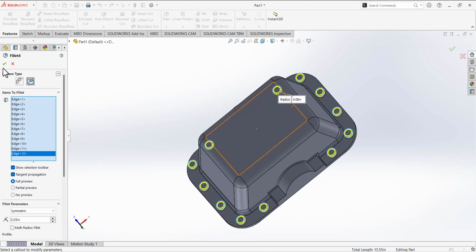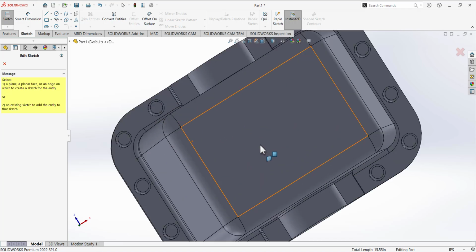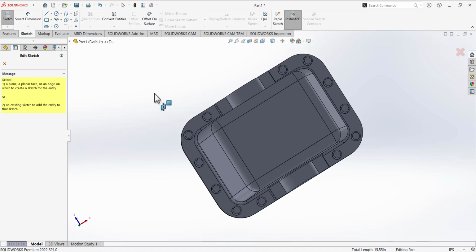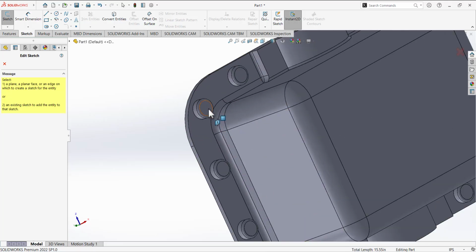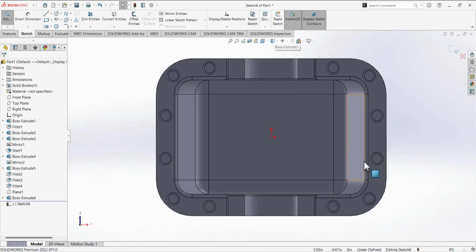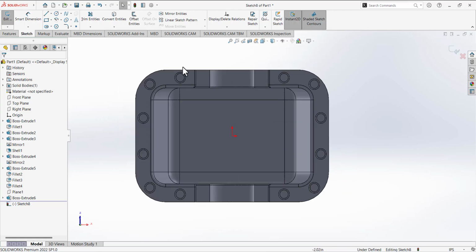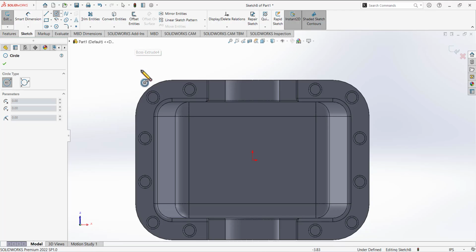Okay, guys. Now open the sketch and make sure when you select the sketch command, it will ask on which plane you want to make the sketch. So basically, we are going to select this surface of this cylinder and then make it normal to you. And then the rest is a simple job. So select the circle tool and move your cursor here on this tab on the edge of the smaller circle if you already added the fillet, and draw a circle.